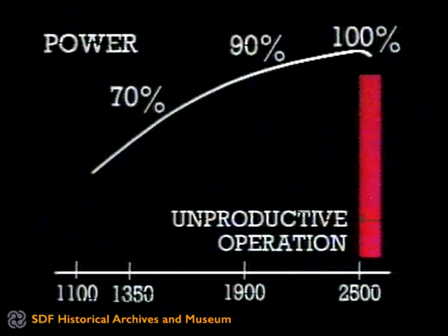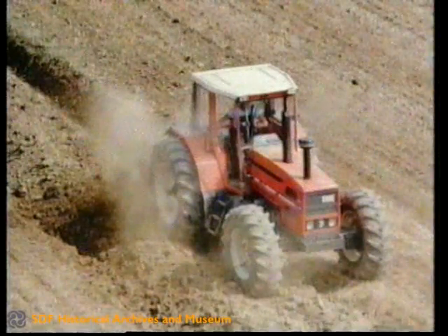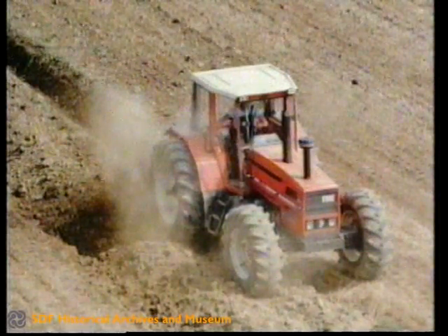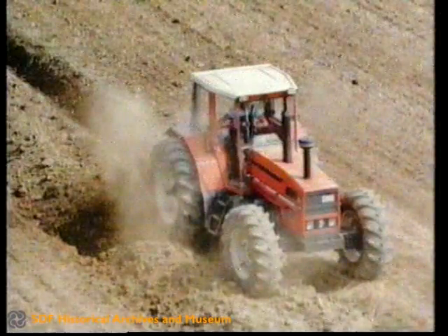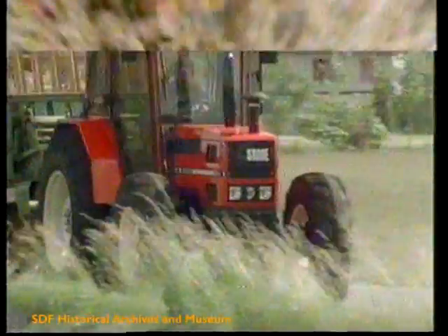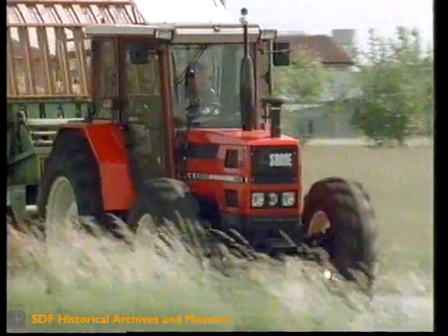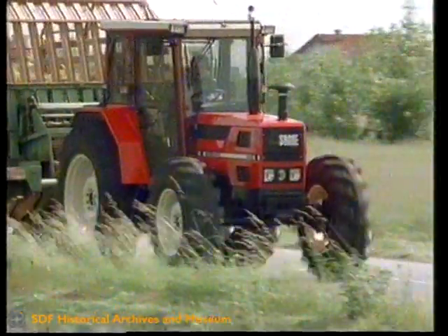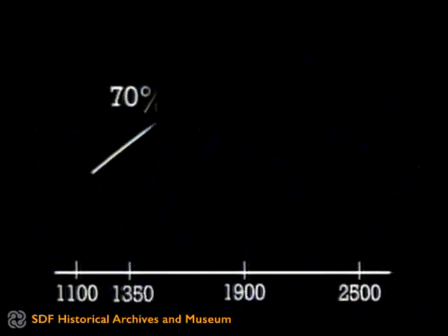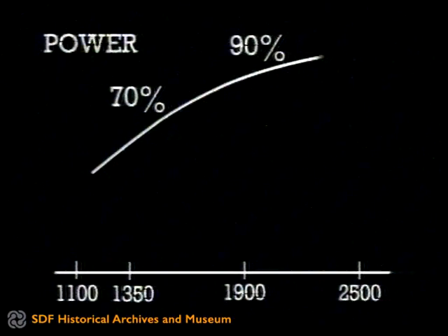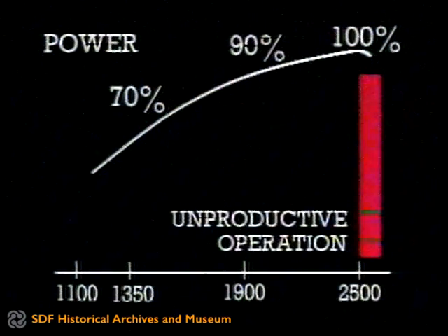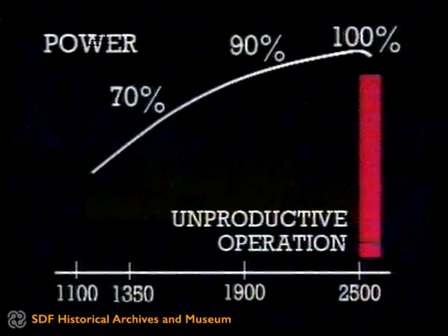Within such a range, it is advisable to use the engine at a speed close to that of maximum output power, when it is necessary to take advantage of full engine power, heavy ploughing, work with power harrow or cultivator. It is advisable, on the other hand, to use the engine at intermediate speeds, 1600 to 1800 RPM, in order to contain consumption as much as possible when the tasks to be done are light. It is of interest to note that in order to obtain 90% output power, 1900 RPM are sufficient, which is 600 RPM below the maximum output speed.